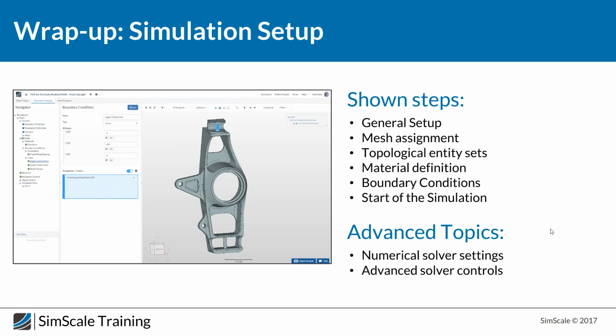The next step was to do the simulation setup, which means we had to choose, first of all, which kind of analysis we want to run. We assigned the mesh. If you want, you can also group surfaces to create topological entity sets. And then we define the material and the two kinds of boundary conditions: our constraint for the wheel hub and the loads for the control arms and the brake torque. And then you just need to start the simulation.